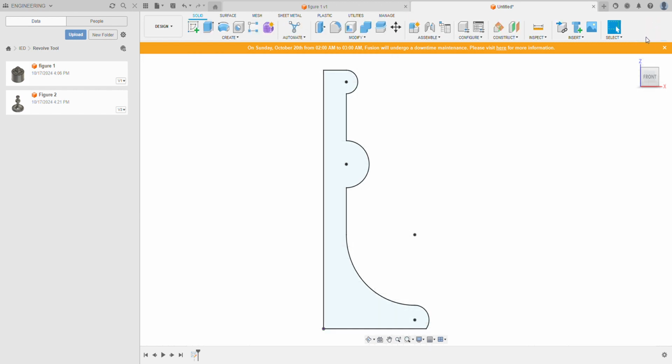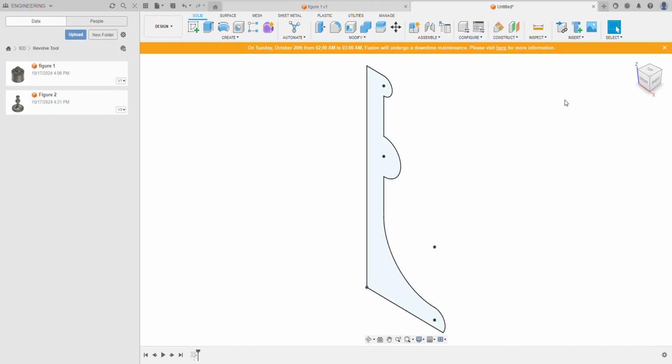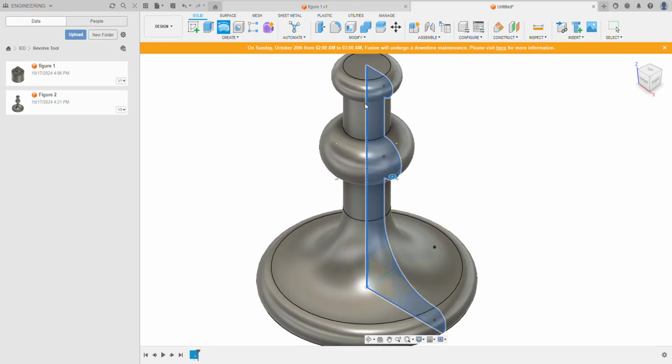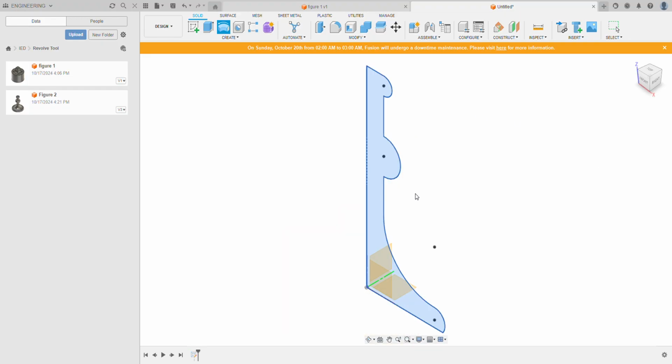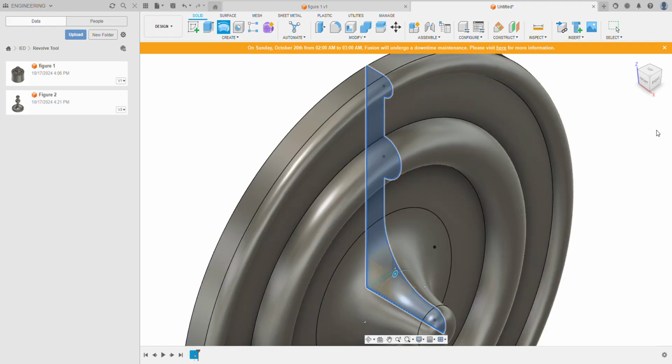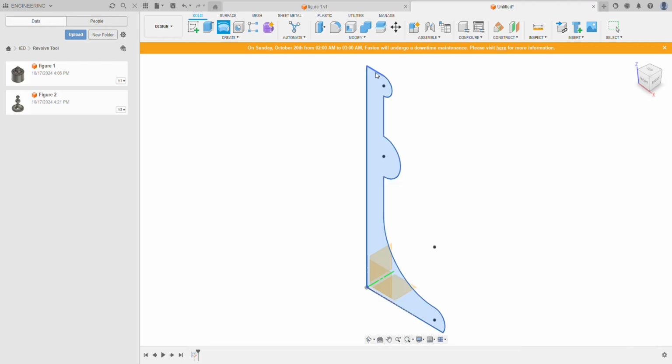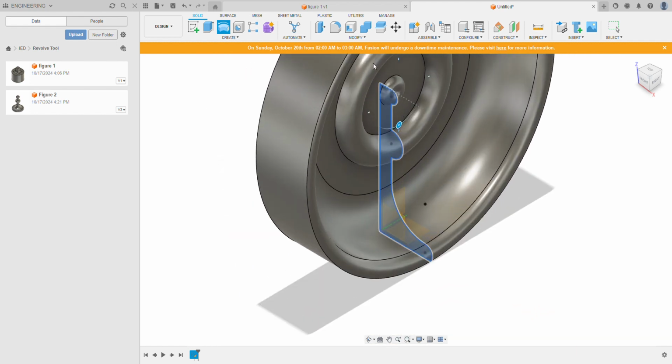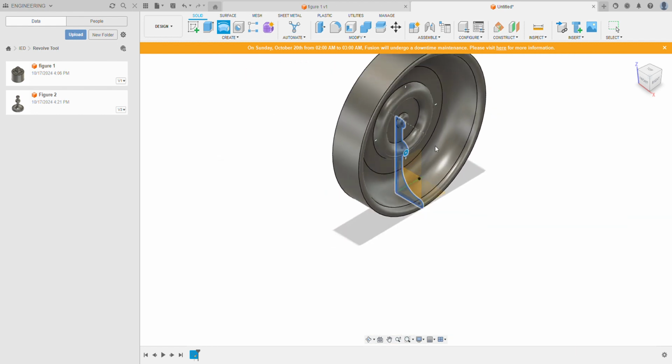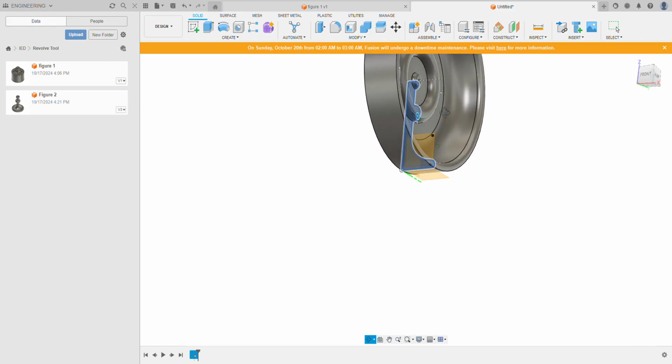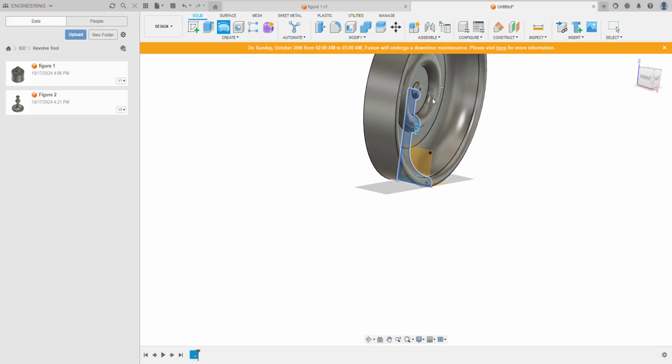If I press Finish Sketch, and I press the Home button, this is the isometric view. We actually see our sketch on our front plane. Now we're going to press Revolve, and I'm going to click the center line. So one thing, clicking the right line is very important. As you see, you can click any straight line that you want, and it will make it. So sometimes if you're trying to make a bowl or a fancy bowl, this ironically would have worked.